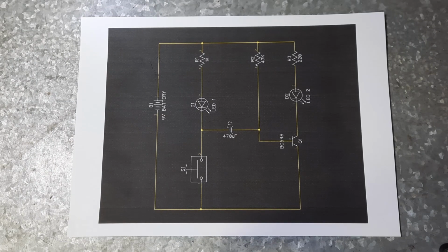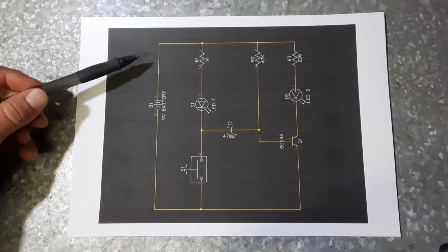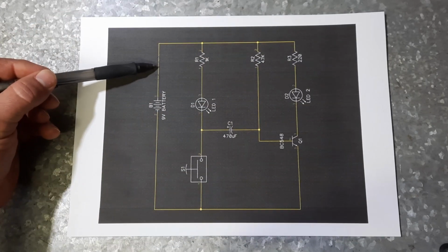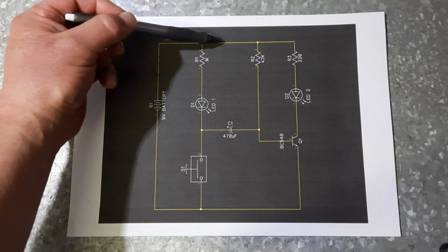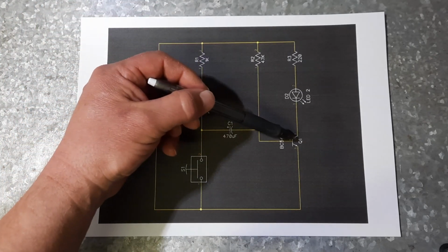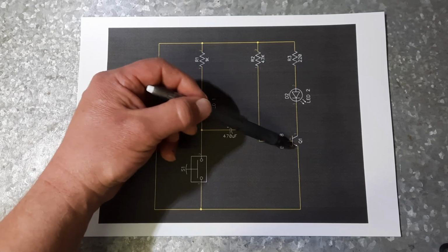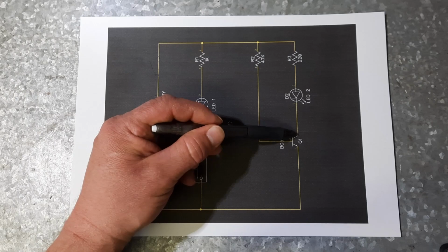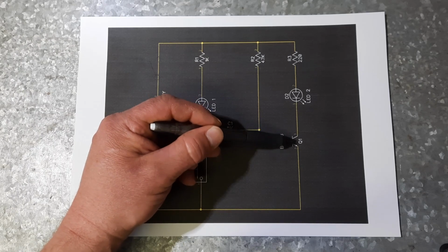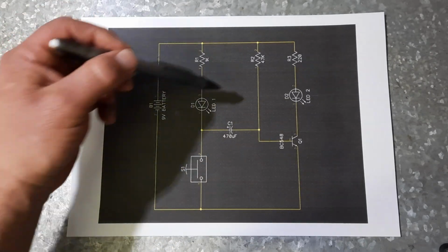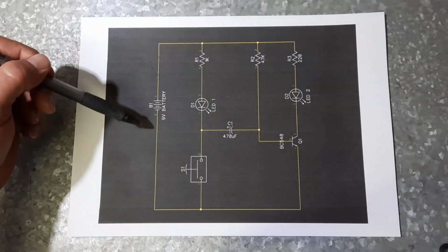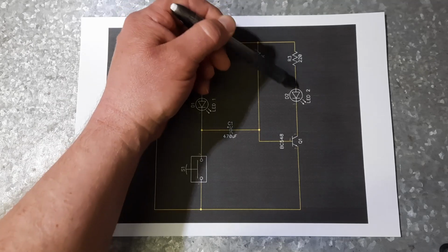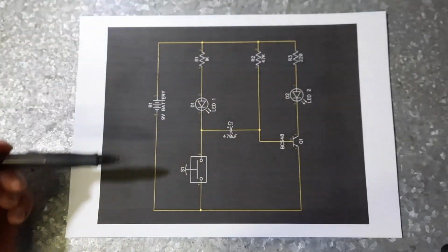So we now know when I close this switch, what's happening in this part of the circuit. We close this switch, power starts to flow from here down through here, which then turns this on or saturates this transistor. Because we're using it as a switch, this is now on. So there's an imaginary wire from there to there. This is running in parallel with that.